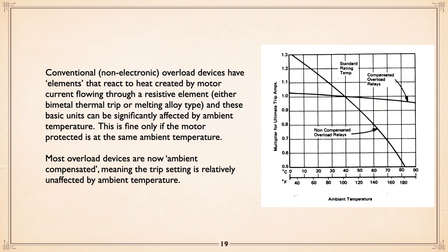The problem being that you're worried about what the motor's seeing, not the overload. If they're at the same temperature, no problem. But what happens if the overload is in a nice cool area and the motor's in an area that's very hot? Well, then that motor is going to see more of a situation.